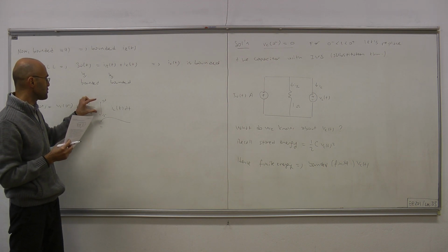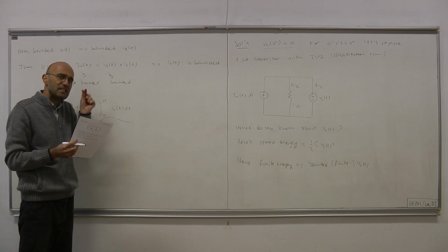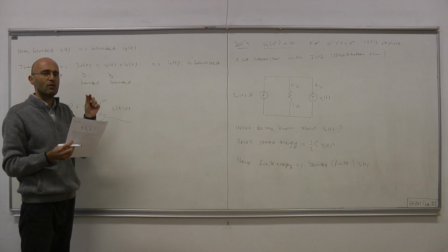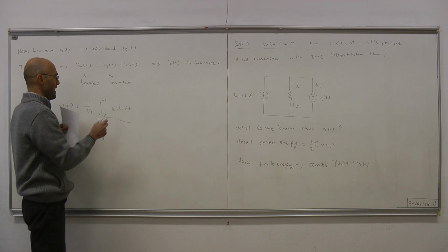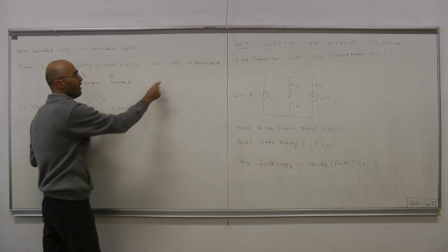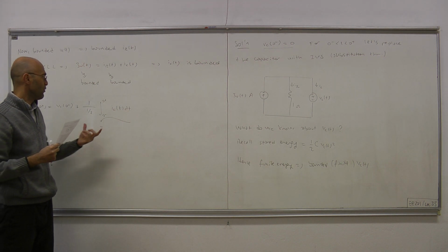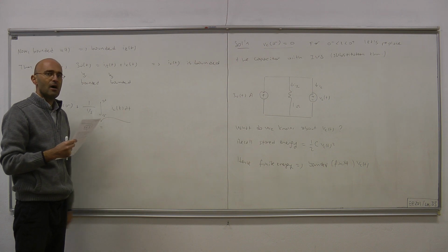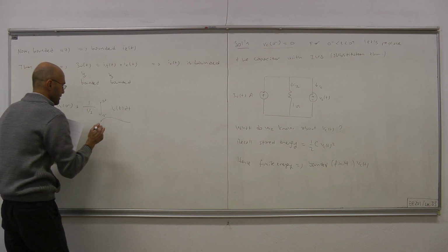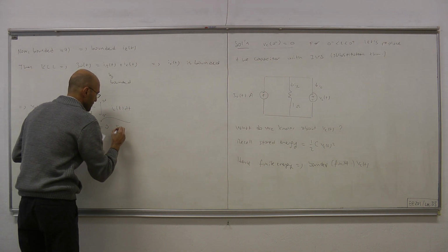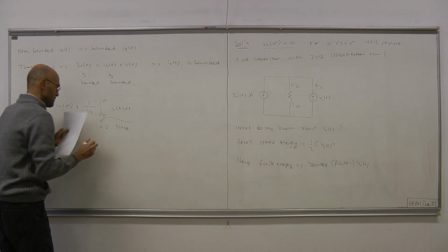It's special because the length of the interval of integration is infinitesimally small. The integrand is our capacitor current, which we know is bounded, and therefore this integral must give us this very simple answer. It must be 0, since IC is bounded.